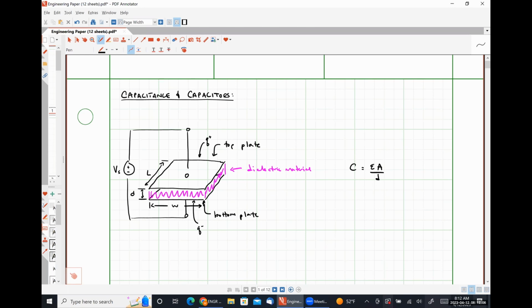So we're always going to see that charge is balanced, okay? Now, the larger that voltage gets, the more charge we're going to put on the top and bottom plates. But it gets progressively harder and harder to place charge on these plates, right? Because we know, or at least those of us that have taken physics 202 know, that positive charges repel each other and negative charges repel each other. So as we try to cram more and more positive charge on the top plate, it gets harder and harder to do so because they don't want to be pushed close together. And the same thing for the negative plate, right?